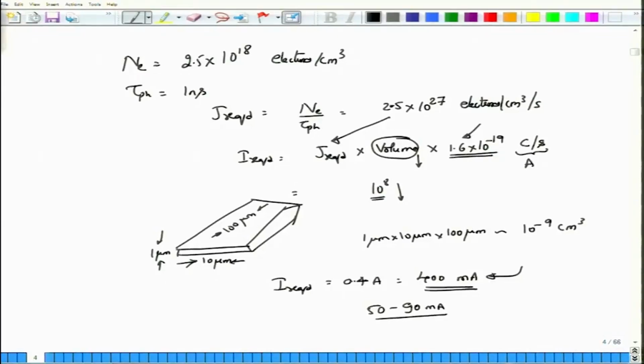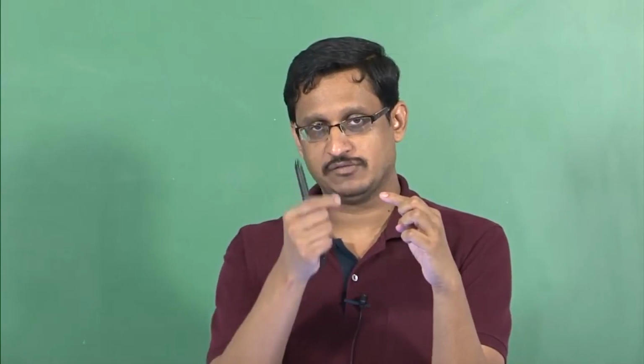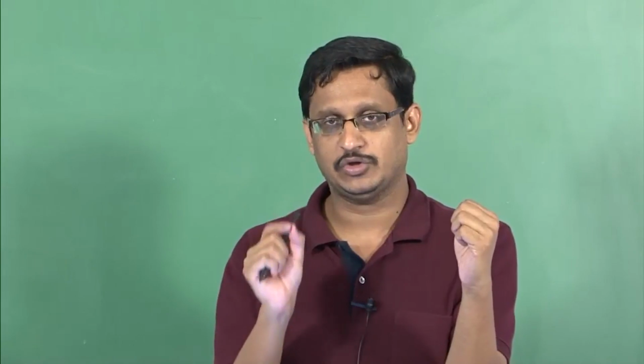Okay. So, the point to note here is that the current requirement of a semiconductor laser diode would depend on the photon lifetime, that is the lifetime of recombination in the material. When you have an electron combining with a hole by making a transition from the conduction band to the valence band, it requires a certain amount of holes or electrons necessary to actually create a situation equivalent to population inversion. It is not really population inversion, because all you are doing is you have moved the electrons from one band to another band, right. It is not like what the earlier laser basic module covered.